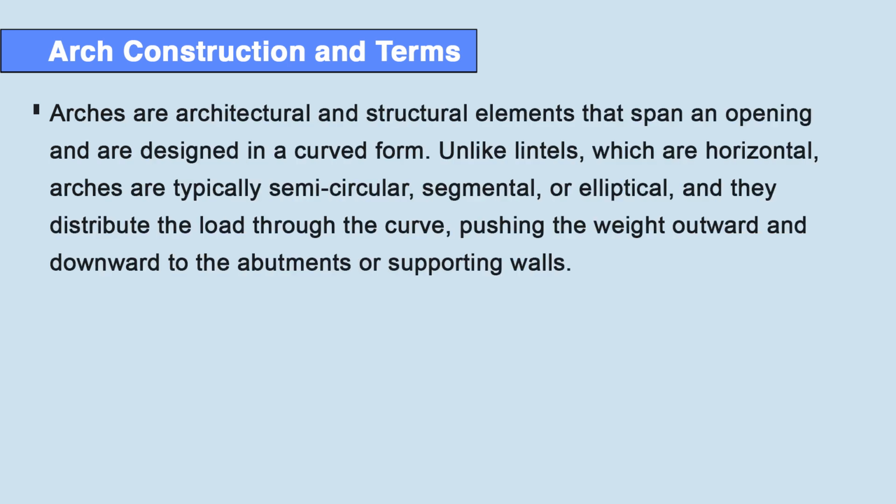Arches are architectural and structural elements that span an opening and are designed in a curved form. Unlike lintels which are horizontal, arches are typically semicircular, segmental or elliptical, and they distribute the load through their curved nature, pushing the weight outward and downward to the abutment or supporting wall. The major advantage of using an arch is that, if we design the arch in the proper manner, the complete arch will be under compressive stress only.